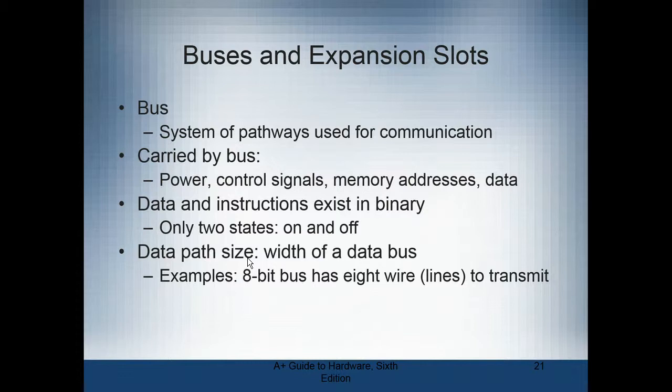Some things take more than 1 clock cycle, obviously. If you have particularly slow peripherals, the processor's got to wait on them, and then it goes into what's called wait states, waiting for the slower peripherals to respond. And that's why in the architecture we talk about the video, in particular, being one of the slow things for us. The closer the video and the memory are to the processor itself, the faster the machine can run, because you don't have to worry about the delays in the bus itself. You're not really using the bus.